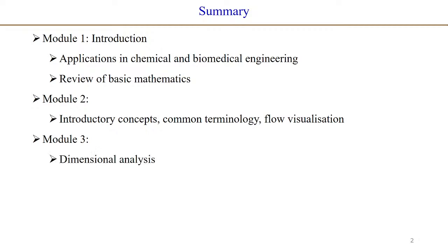In the third module, we discussed the simplest yet powerful technique to analyze a fluid flow problem. The power of the technique is that you can do the calculations quickly, and we call it dimensional analysis. In dimensional analysis, we can list down all the parameters on which a particular flow phenomenon depends, and then we can group those into non-dimensional parameters.